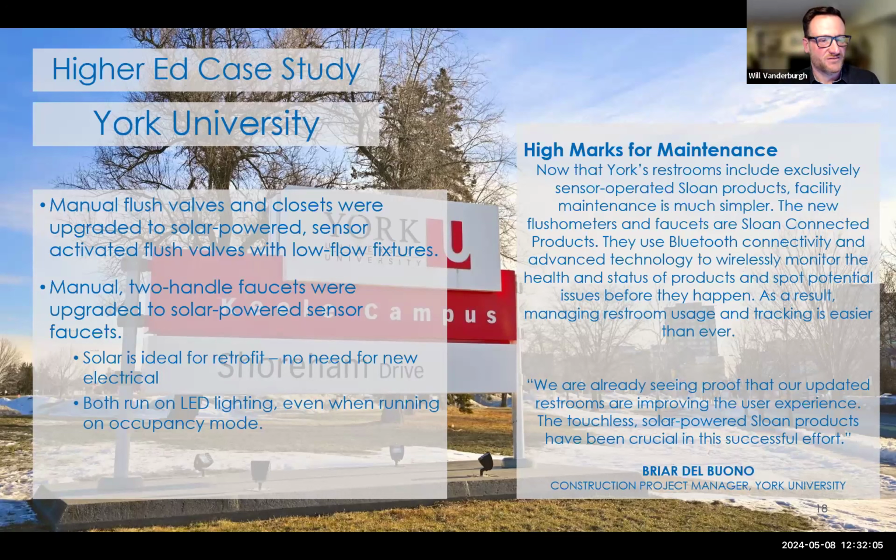So in terms of the water closets and urinals, they've all gone to a low flow technology. In some cases, they were using 3.5 gallons per flush. What does that translate to? Oh, upwards of 15 liters. 15 liters of water per flush in a lot of their washrooms. They've now gone to 4.8 liters per flush. Their urinals are down as far as 500 milliliters, so half a liter. So that's a dramatic water savings right across the campus.